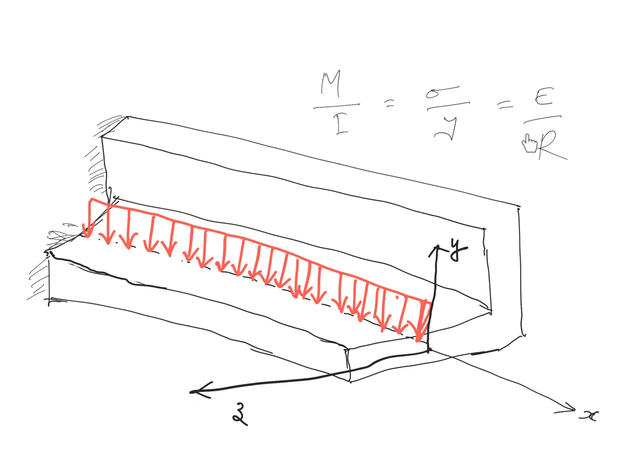This particular equation is not applicable here, because as you can see, the loading plane is not symmetric about the cross section. The cross section, which is kind of L-shaped, is not symmetric. The loading plane is not symmetric to the cross section. So Euler-Bernoulli theory is not applicable in this scenario. But there are workarounds where you can shift the force to the plane where it is symmetric, and you can do all those things, but in its purest form, Euler-Bernoulli theory is not applicable in this case.